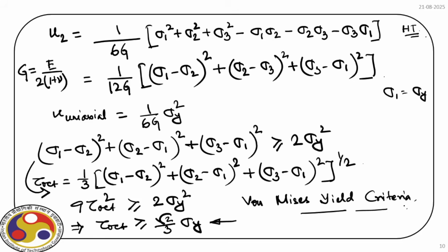So with that, let us conclude our discussion on different failure theories. What you have noticed is we start with the 3D stress field and then we quantify principal stresses, and then we find out the maximum conditions and equate it to the uniaxial test, and then we derive different criteria that quantifies the failure of a material. And that's how we developed all these different theories, and some of these theories agree with test results very well. Some of these theories are very conservative.